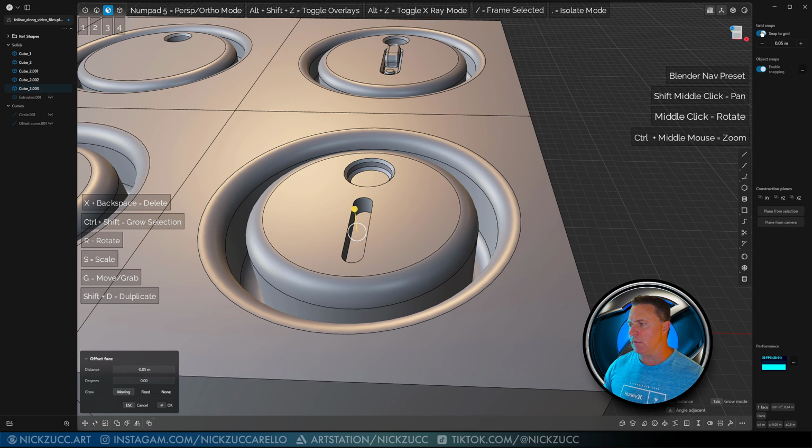Now, this might fail on me if I change these, but you can see this is set to G0 on all these. This is considered tangency. G0 is going to be a nice flat corner piece like that. But if it's something like G1 or G2, that's going to try to do a nice transition and a nice smoothness through there. Let's just see what happens. Yeah, it looks like it's going to fail on there. But if I do G1, let's just do G1 all the way around the whole thing. Doesn't really look appealing in this case, but there might be some cases where you might actually want that. But I'm just going to put this at G0, G0, G0. I just wanted to show you the options for that, and you can see what it's doing there.